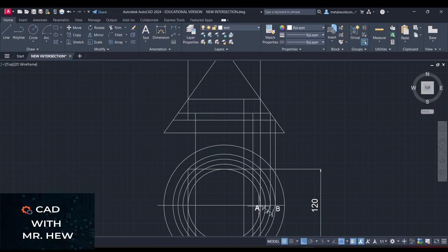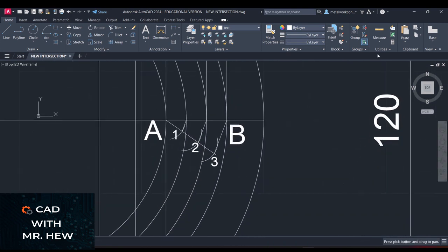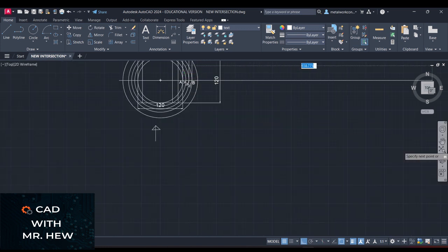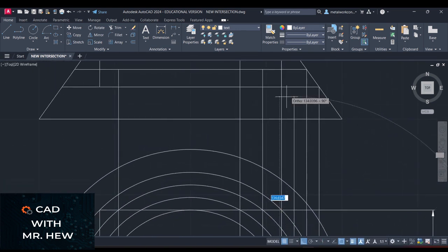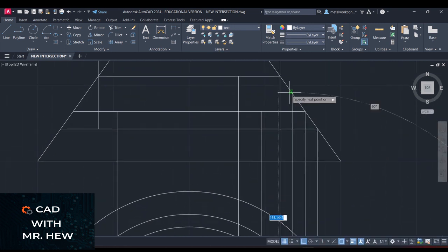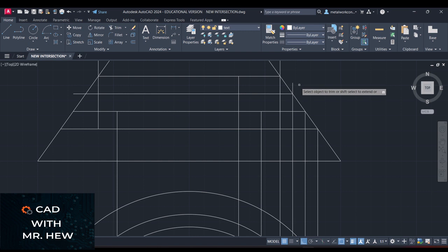I'm going to do the next side. What I'm going to do is project up the second disc, which is this number 1 right here. Look now, I projected this one. I need to project the line going up here. So let's do that now. Line here, going up to the side of the cone to get the disc, which is there. Enter. We're going to draw a horizontal line to represent the disc in the front elevation. Enter. We're going to trim to let our drawings look neat and sharp.